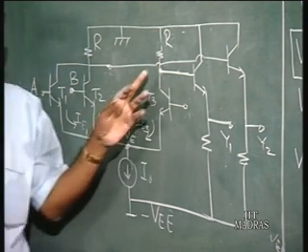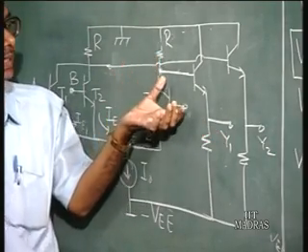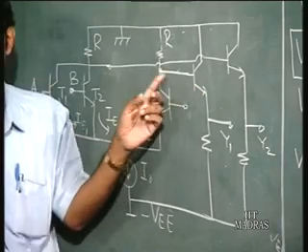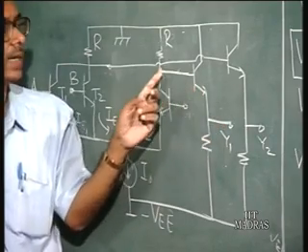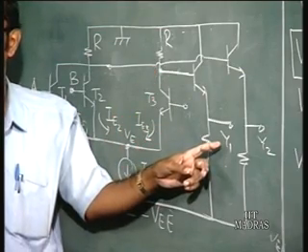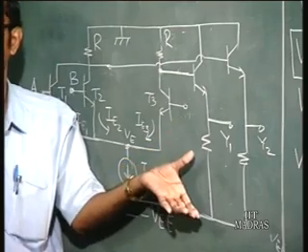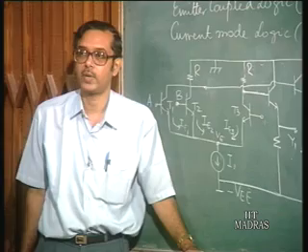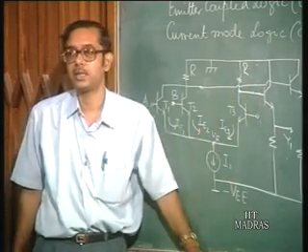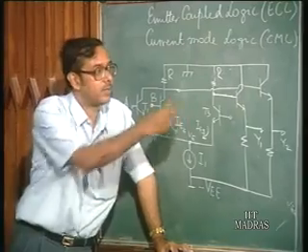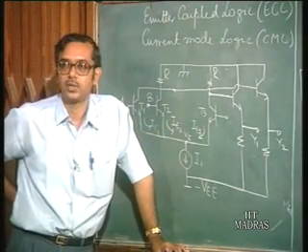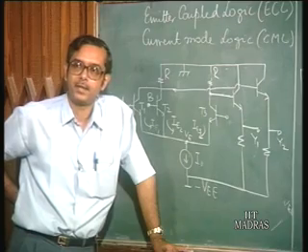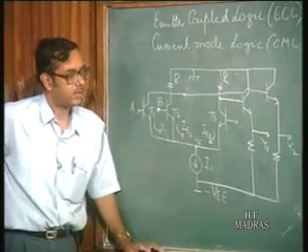So here now, what is the output voltage variation? It is basically shifting the output voltage by V on. Now when the voltage at the base of this emitter follower transistor is 0, the output is going to be minus V on, and when it is minus V on here, it is going to be minus twice V on. So it is basically shifting the voltage down by V on. The output voltage variation now is going to be from minus V on to minus twice V on. And that is our requirement for this ECL gate. We have seen Vi should be Vr plus or minus half V on, and if Vr is minus 3/2 V on, the input voltage should vary from minus V on to minus twice V on. So you see that this effectively solves our problem number 1.